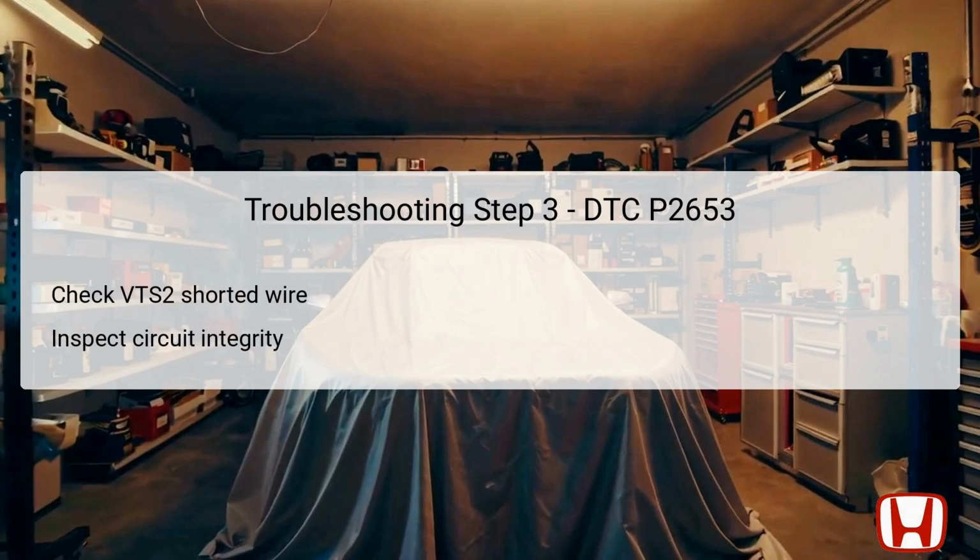The third troubleshooting step involves checking for a shorted wire in the VTS2 circuit. This is a critical step, as it helps ensure that the circuit integrity is intact. Begin this process by disconnecting the PCM connector along with the rocker arm oil control solenoid connector. This will allow for a clear inspection of the wires and help determine if there are any shorts to ground or openings in the wiring.